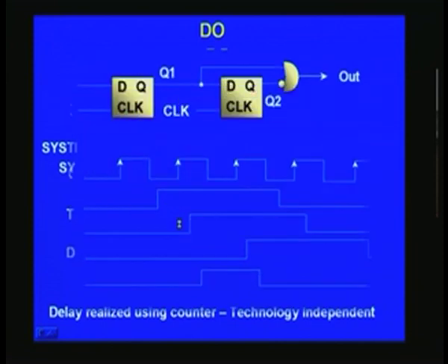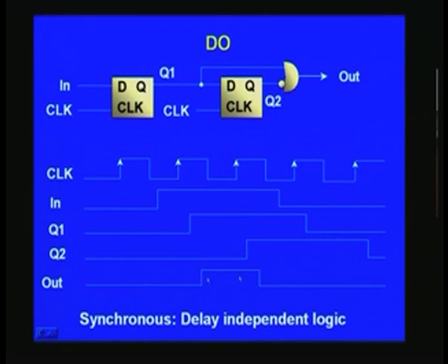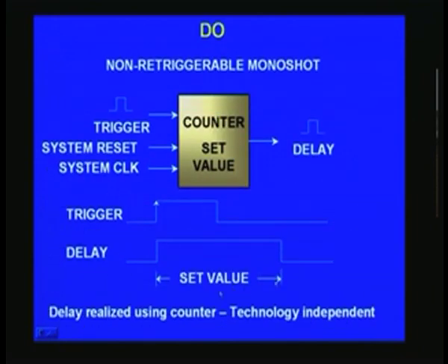So you can see in the previous case, this final delay is based just on the clock and not on the technology. So even if technology changes, any future technology that would come, your design investment that you have made, had you adopted one of the two schemes, is still preserved. So that is how we say it is a technology independent design. So a designer will have to keep all these do's and don'ts in mind prior to actually designing any circuit.